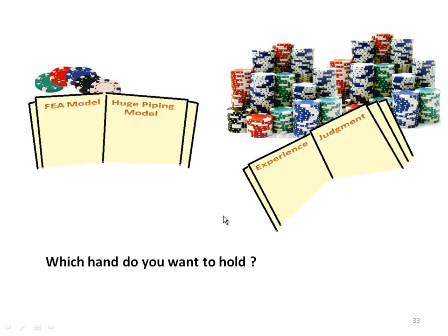We'd also like to emphasize that experience and judgment trump large FEA models and weeks of piping model building. You have to know what to expect and build models to validate that anticipation. You can adjust the density of a finite element mesh so that results are within 5%, but we do not want to pretend that we're predicting the stress for a piping system in a fossil or a chemical plant to within 5%. And that has nothing to do with the software that we're using.